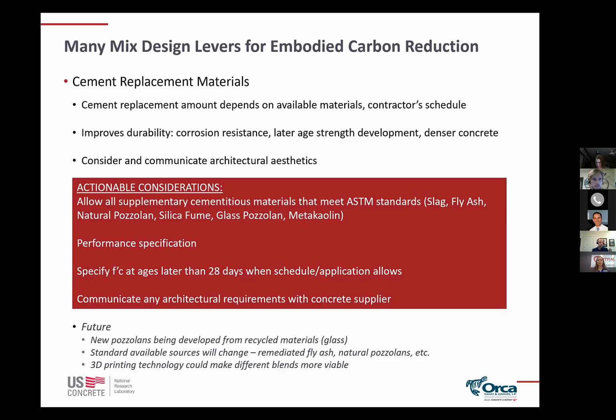Things to consider for the future: there are new pozzolans being developed. So I mentioned glass pozzolan. That's something that an ASTM standard is newly coming out for. That's not something that's readily available in the country. There's a source in the New York market that I'm aware of, and that's the only one that I'm aware of right now that's available out there.